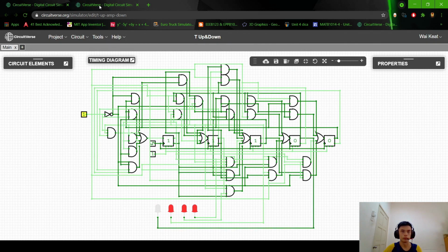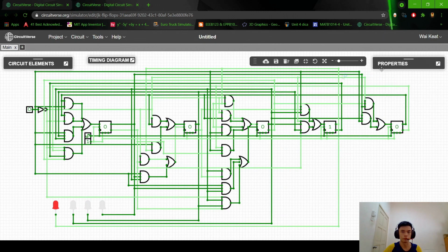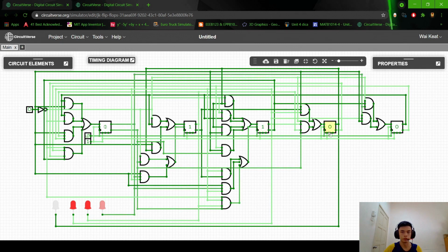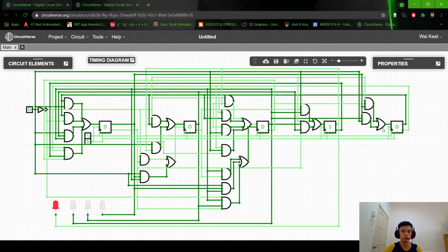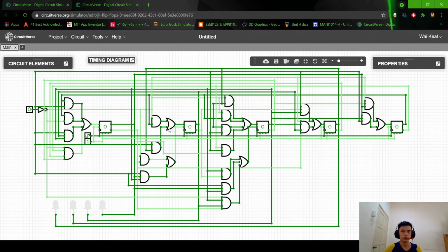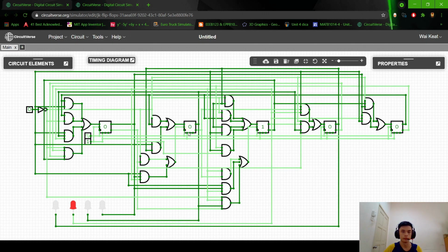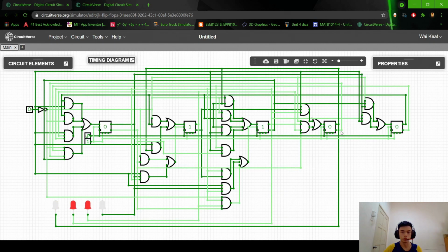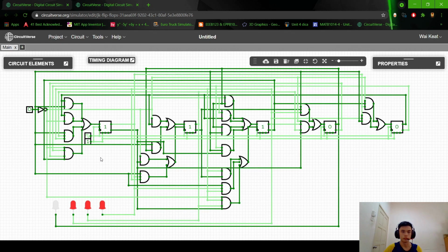Same for the earlier design, using JK flip-flops, Q1, Q2, Q3, Q4, and Q5. We didn't put LED on Q5 because we don't need the values of it. We only need it to generate the second zero in my ID number, 0, 1, 0, the 0. So same, this connects to Q4, Q3, Q2, and Q1 respectively. And that's all from me.